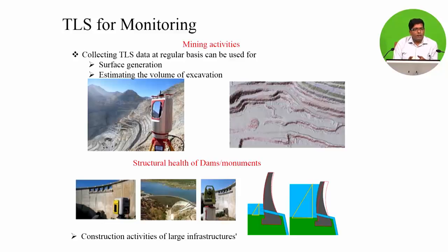Very important structures like dams and bridges can be monitored to assess their health, and if the health is deteriorating, then suitable measures can be taken so that we are maintaining the required strength of that monument. So here we can do the scanning of the dam from various points, and then we can make a model of the dam, and then different loads are applied on the model, like the water level. If the water level is increasing, then what should be the allowable deformation in the dam, and if the deformation is more than the allowable, then suitable measures have to be taken so that we are doing the conservation of the dam.